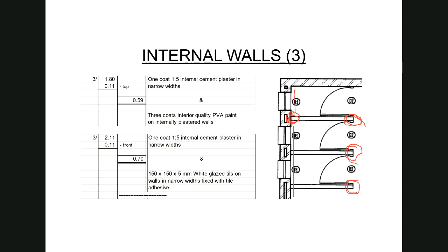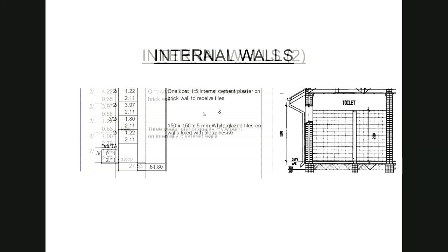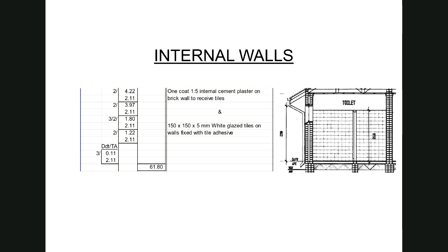Let's say, for instance, these were 1.5 brick walls that are 330 wide. It wouldn't have been necessary to do that distinguishing, but because this remains a narrow width which is smaller than 300, I now need to do that. But because I have measured over those walls, I need to do the deduction over there. Okay.